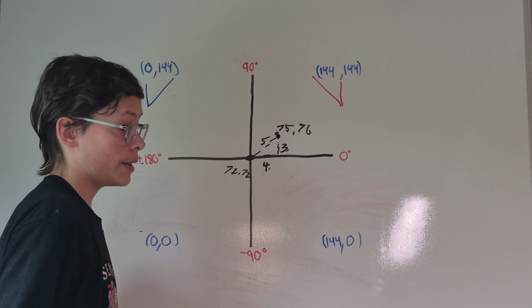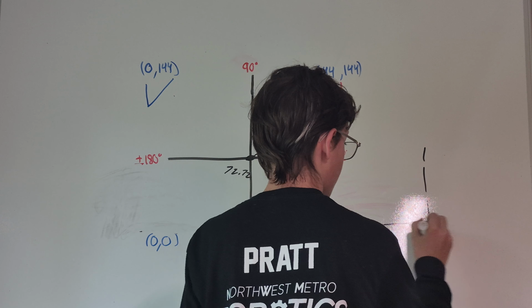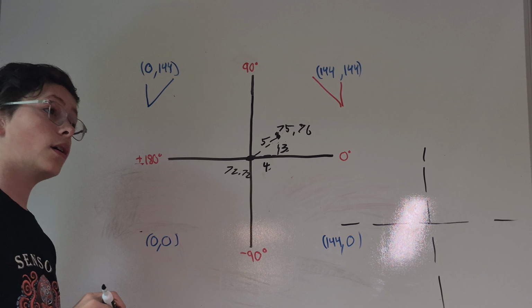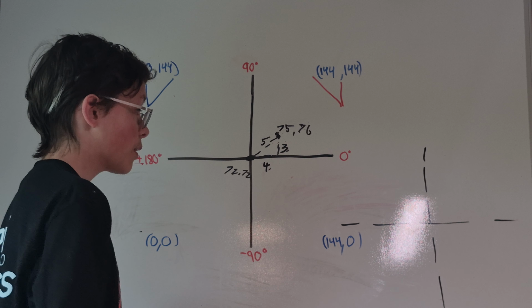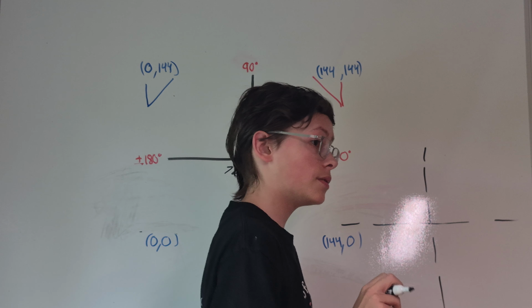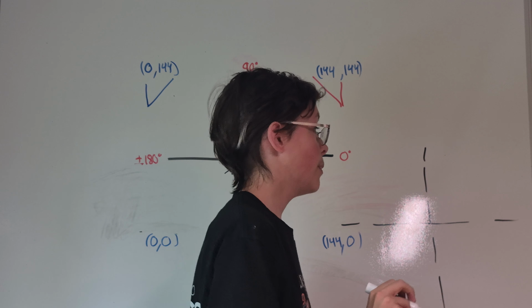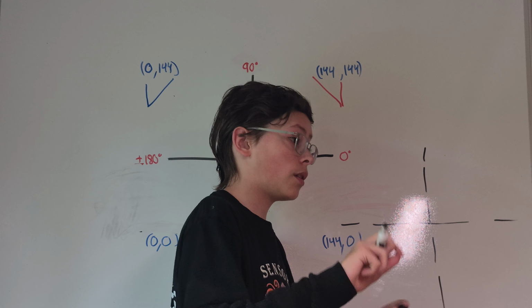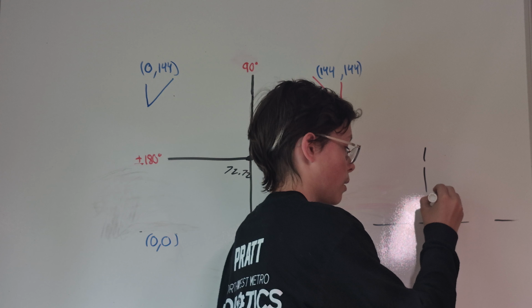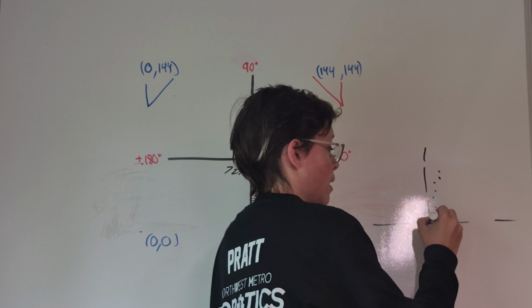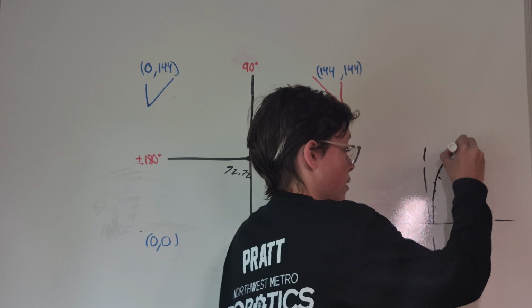So now that we have our distance, what we need to do is get another graph. We need to run it through an equation to turn that distance into a motor power. What we did for this is we set our motor speed to something in our old teleop, moved the robot back until it worked, and then recorded the distance to the hoop, and we kept recording distances. We recorded, I think, about 6 of them, and eventually we got ourselves an equation.